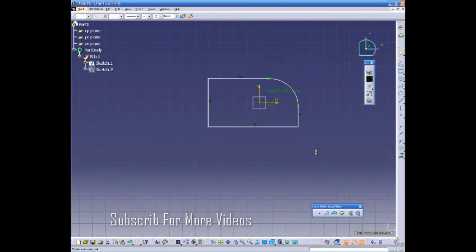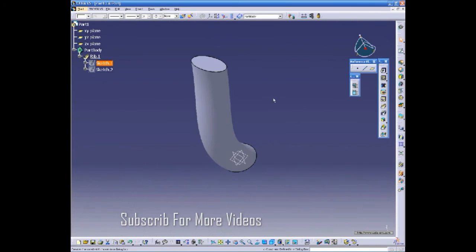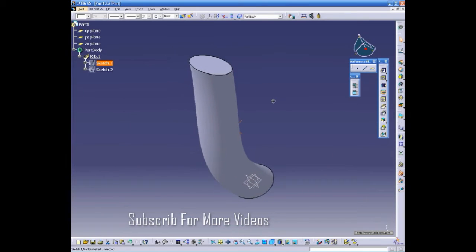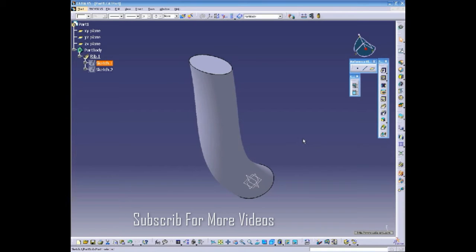Delete the rectangle and create a circle, then exit the sketcher. You can see the geometry is updated according to the new modifications. Okay then, let's undo the last two operations.